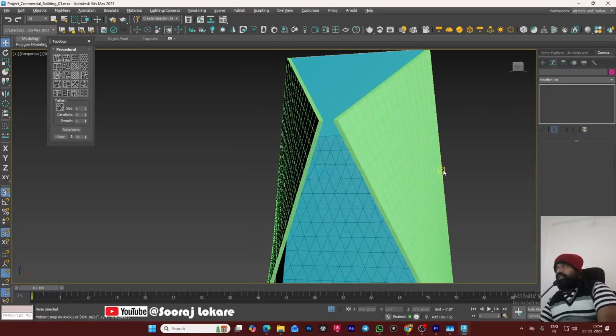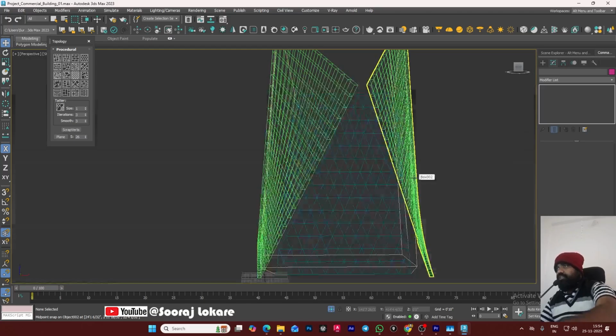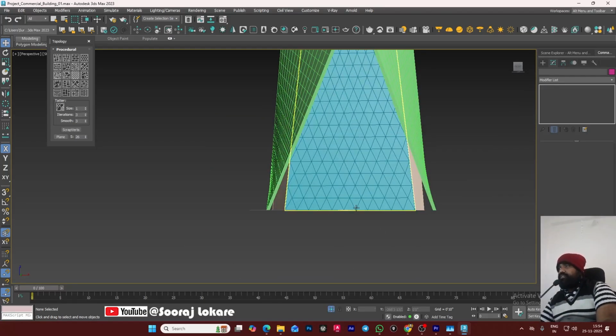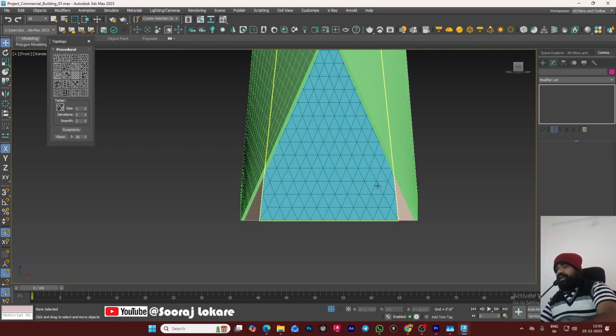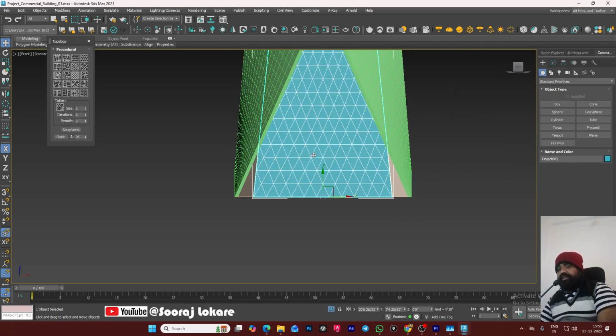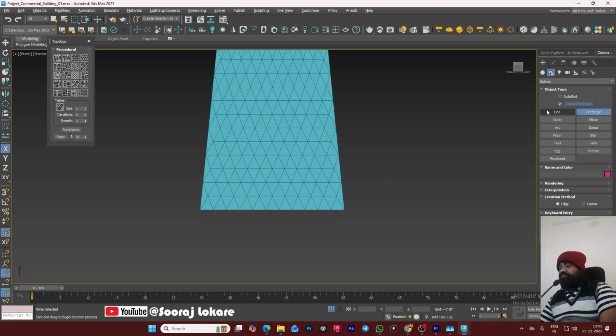Yeah, so for now we got this glass railing pattern for our front section, and we need to add some entry here. For the entry I would like to do something. I select it, press Alt Q, and make it isolated, and we need to add a 2D geometry for reference.